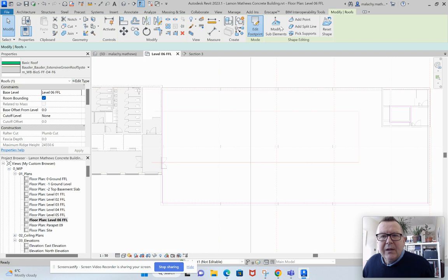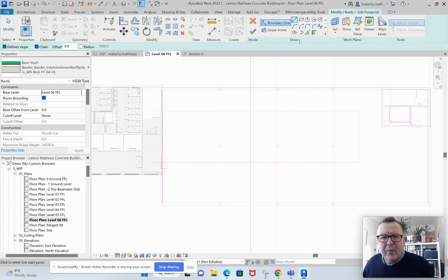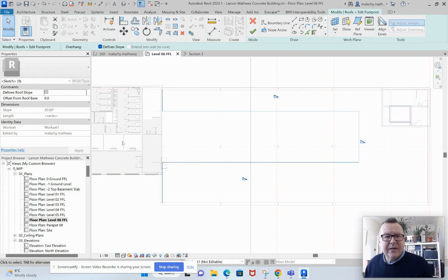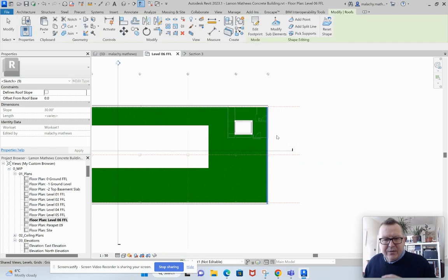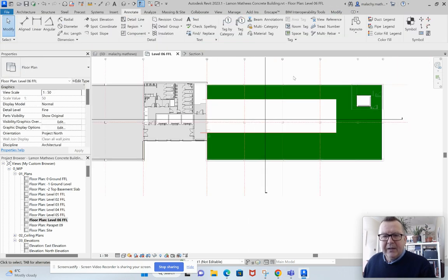Edit the footprint. And so we just do a pick line with these. So do that one again. And it's your construction lines here. And we'll do a split at this point, and we'll do our fillet here. Okay, and escape once, and then select these lines here and knock off the define slope. Right, don't attach. Now, so I've got a gap happening there.